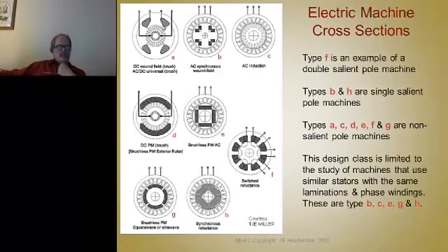armature. Now, what's interesting to note, even by looking at this picture, is down here we have a permanent magnet version of this. Here's a permanent magnet version of that. Instead of this wound electromagnet, North Pole and South Pole here, we have a permanent magnet. Now, there's no wires connected to that, so the flux from this permanent magnet is fixed. The field, or the flux that comes from this electromagnet, can be adjusted.